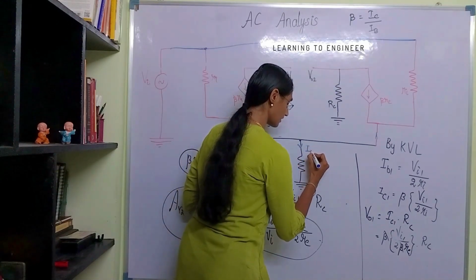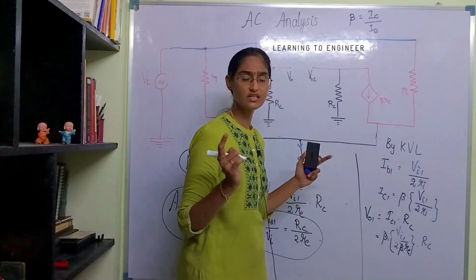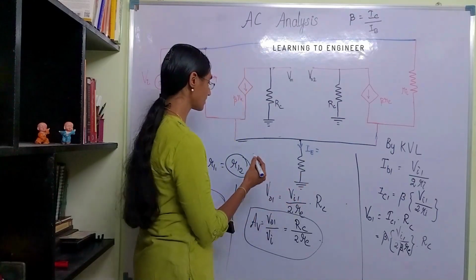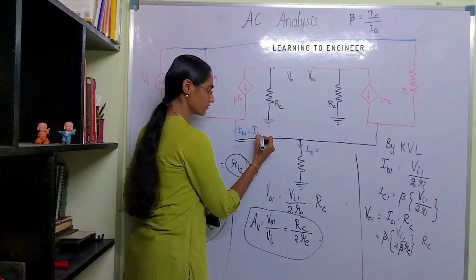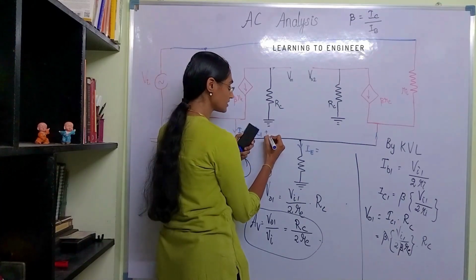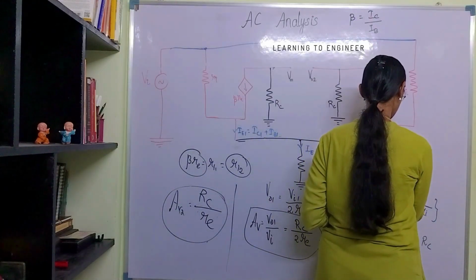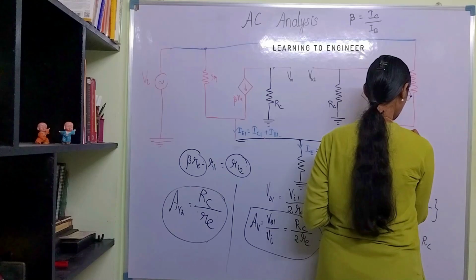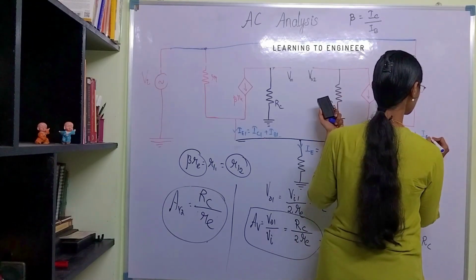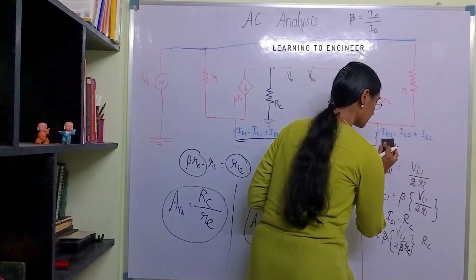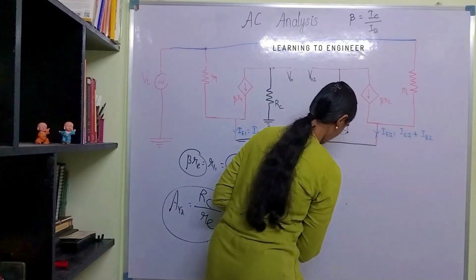This is IE. What is IE? Base current plus the collector current by general definition of a transistor, right. So what is this IE1? IE1 will be IC1, this collector's current, plus the base current of this. So what is IE2? IE2 will be this collector's current plus the base current of this, okay. I will rub everything, and now we will see the common mode gain.